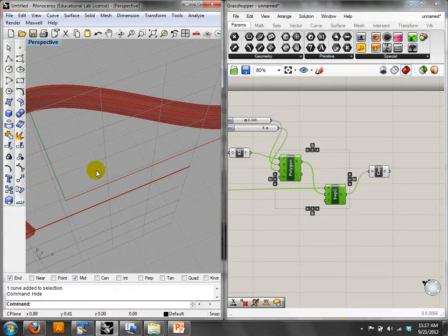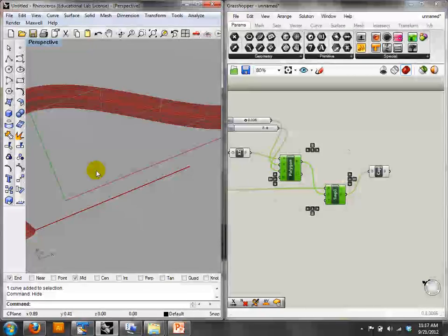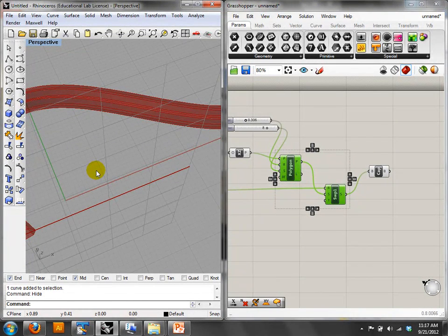If you need a square section to do something, for a window mullion or for whatever, you can do a sweep if you have an angle or some kind of a curve. If you just need something that's straight up and down, sweep doesn't really make a lot of sense, right? You just want to extrude that square up and down, or in and out. Okay.